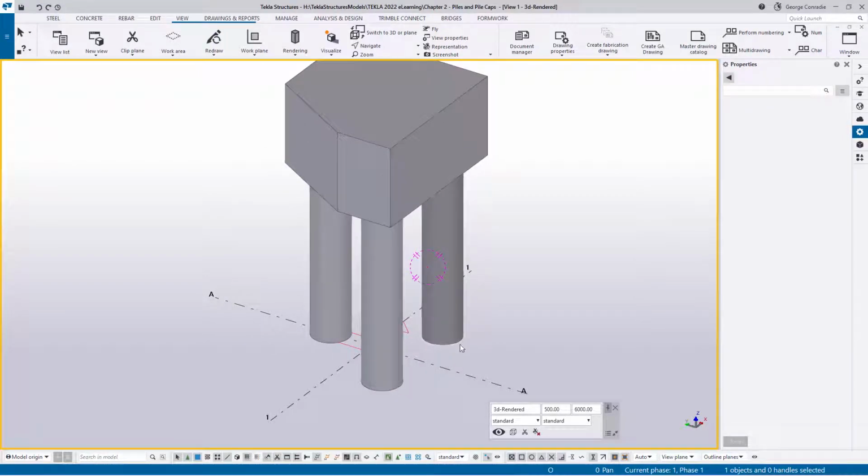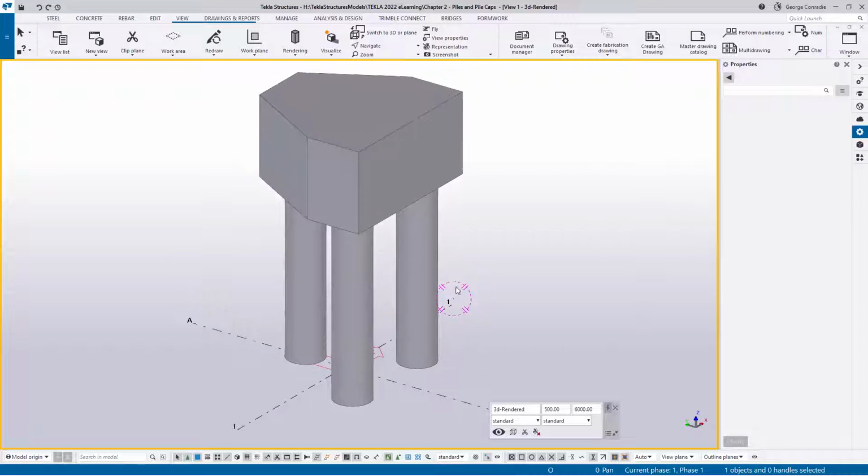The first being a custom component, the second one using rebar groups and single bars, and the third one, rather than showing a method, I just want to highlight why I would not use rebar sets on this, because with rebar sets and circular columns, there's a problem with the ligatures in the lapping, but I'll highlight it when we get there. So let's start with the first pile, and what I want to do is use the custom component.